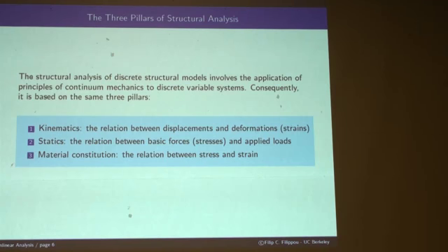And I can set up, as you will see, templates so that I can do any 2D frame element you want, I can put a template together and you have it. But a 2D frame element that does torsion, shear, and axial force and bending moment takes a constitutive model that is robust and accurate. And up to this day, I haven't seen one that is robust, accurate, and fast. I have seen accurate and very slow, accurate and non-robust, and so on. So all three ingredients are sometimes difficult.